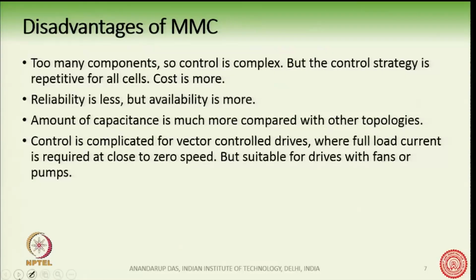Now, MMC has a very high initial cost, because of building the converter, testing it and making it work. So, it is a very high initial investment, but at running condition the efficiency of MMC, you may be surprised to know, is very close to or even more than 99%. So, the running cost or the losses are less in MMC, and so it is advantageous when we talk about the operational reduction of losses.